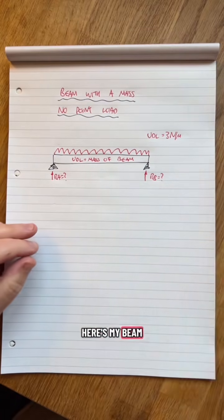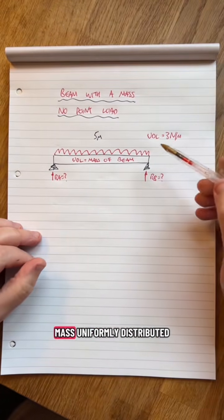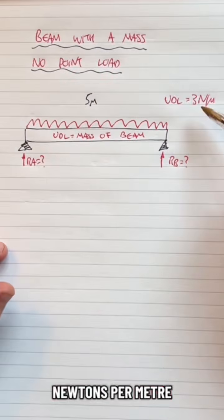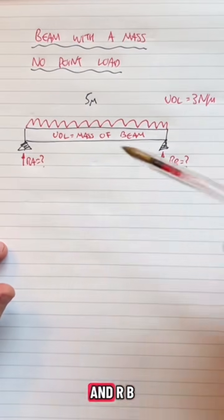Here's my beam. I'm going to give it a length of 5 meters. It's got a UDL, which is equivalent to the mass. Uniformly distributed load of 3 newtons per meter. That means it's 3 newtons every meter. This thing's in balance, I'm going to assume it's in balance. We need to find RA and RB.